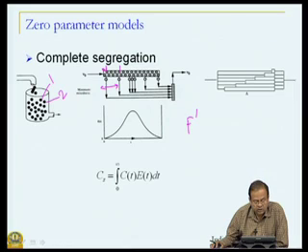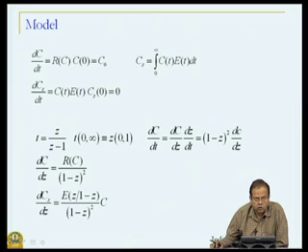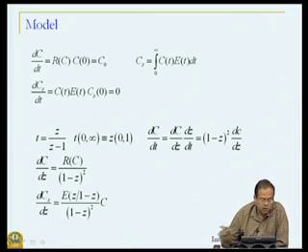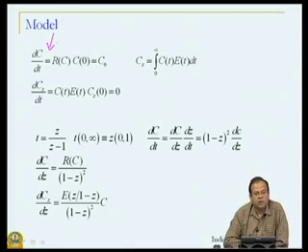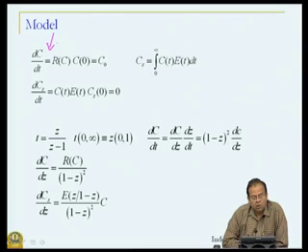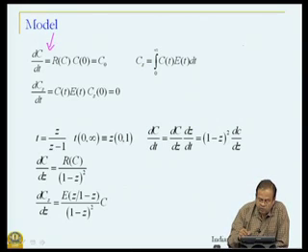Okay. So, that is one way of looking. If we take a model, for example, let us say that we have a reaction and its dynamics is given by dC/dt equal to R of C. Now, what we are saying, for example, is that a fluid element of a certain age spends that much amount of time and comes out.